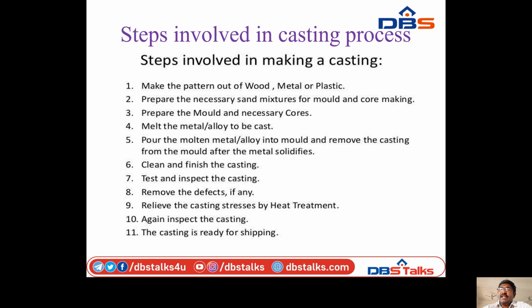Clean and finish the casting. Test and inspect the casting. Inspect the casting. Remove the defects, if any. Relieve the casting stresses by heat treatment. Again, inspect the casting. The casting is ready for shipping. So these are all the steps involved in casting process.